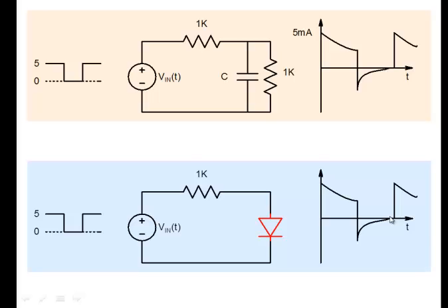Now you can also think, what if I change this voltage rapidly? What will happen? Suppose I change it rapidly so that the frequency is right here at this point. I switch it off. What will I see here? I will see almost like a square wave here, because before it discharges, I go to the next cycle. So I will see as if the diode is conducting very large current in the reverse direction also. You will not see this particular part here if the frequency is high.